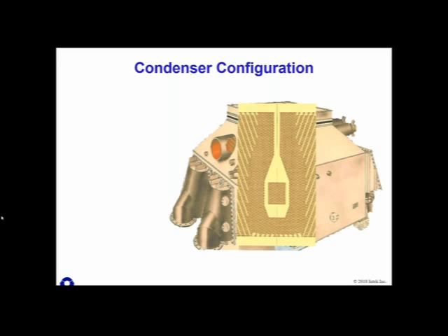This bundle arrangement plays a large role in efficiency and performance of the condenser because the patterns determine steam flow patterns, condensate management, and most importantly, the efficiency of air removal. So for example, in this bundle, you can see lanes, steam lanes. I'll show a couple of different designs with different lane configurations. You see the air cooler section, that's this central rectangular section of tubes right here.